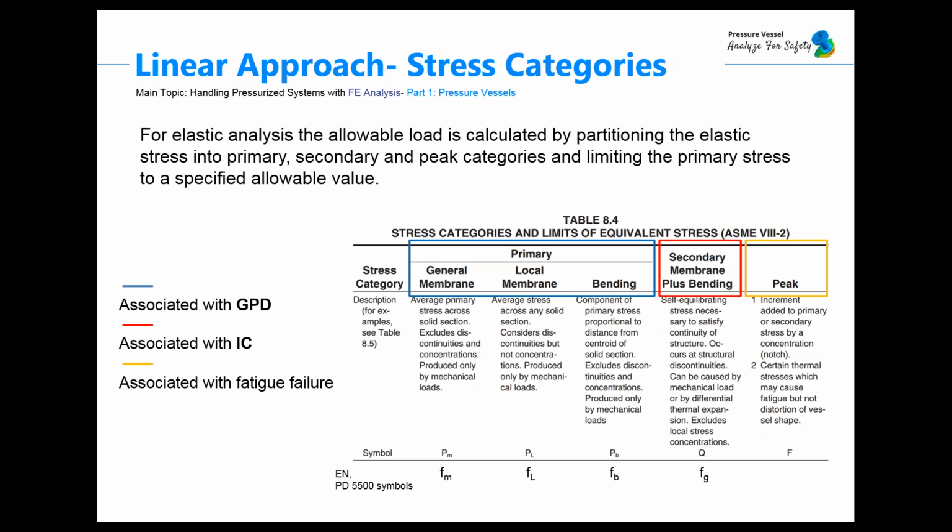Based on the loads, elementary stresses are calculated at all points that are in scope of the analysis. In a three-dimensional case, these elementary stresses consist of a vector of 6 components of normal and shear stresses, which finally should be classified as membrane or bending stresses. The code categorizes the stresses into 3 categories, and the main task for the designer or FEA engineer is to classify resultant stresses into the right category. From this moment, let's talk a little bit about those stresses.